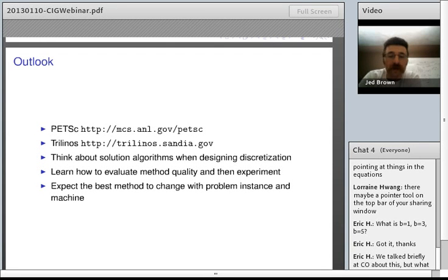The question here is about preconditioners for matrix-free methods. And you almost have to do multigrid in that case. So you can do local preconditioners like Jacobi and Gauss-Seidel, but those won't converge well. So you're almost required to do a geometric multigrid. You can do just one or two levels of geometric multigrid and then switch to an algebraic multigrid, and that's a fairly effective method. The matrix doesn't cost nearly as much on the coarser grids.